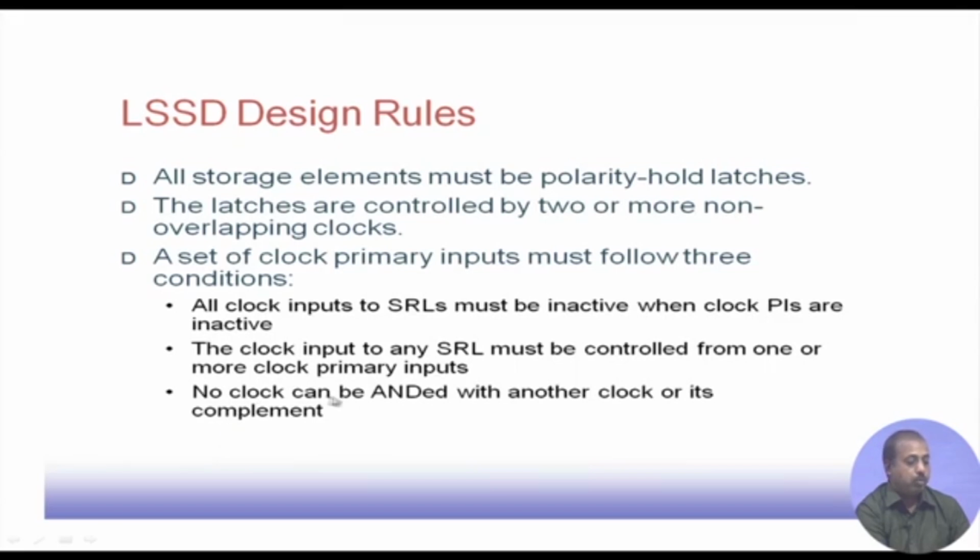And the second thing is that no clock can be ANDed with another clock or its complement. If you AND them, there is a problem, because the operation becomes difficult to predict, like how to enable or disable the clock signal. So, that logic becomes complex.